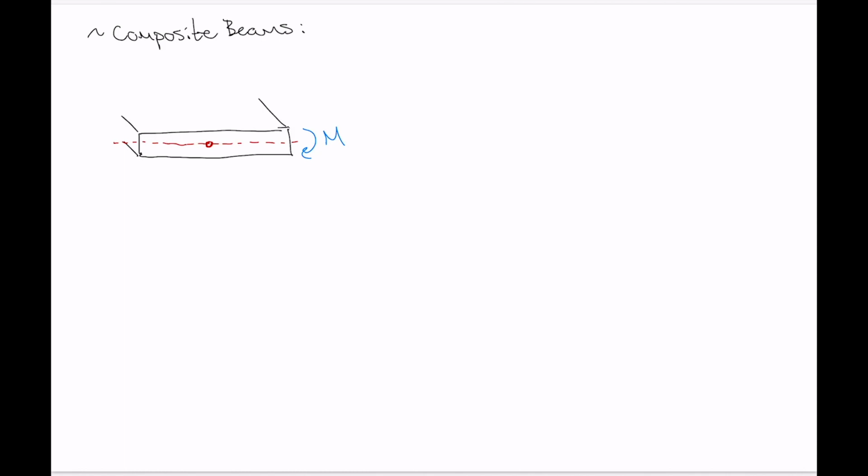We know that bending stress, sigma, is My over I. And for a rectangle, I has the term h cubed in it. So our normal stress is proportional to 1 over h cubed in this case, where our height is this dimension there.